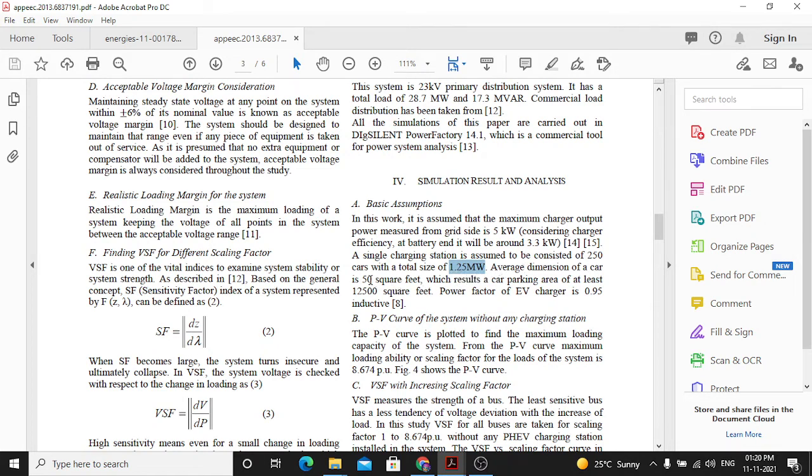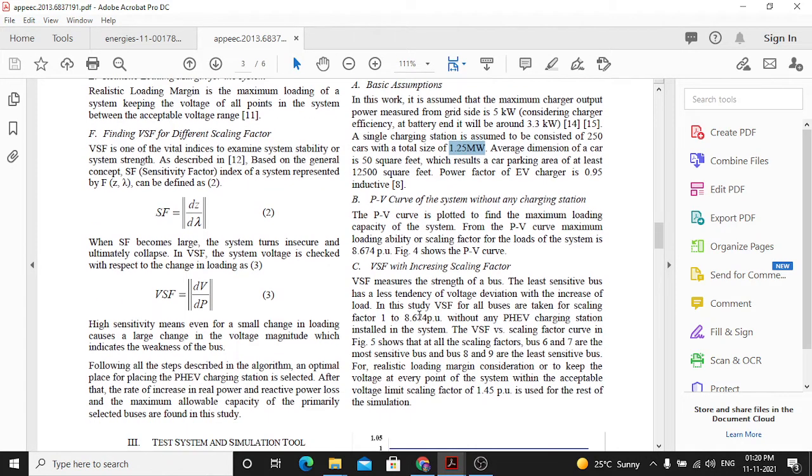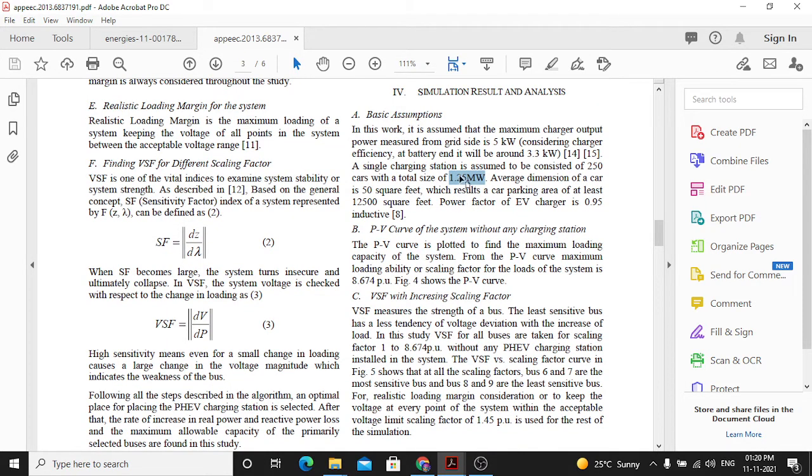So this Te, the torque developed inside the electrical machine, is directly proportional to the square of the stator voltage. The stator terminals, you can see, are connected with the PCC. So the PCC voltage is decreased during this fault. If the PCC voltage is decreased, then the electromagnetic torque produced inside the electrical machine is also reduced.